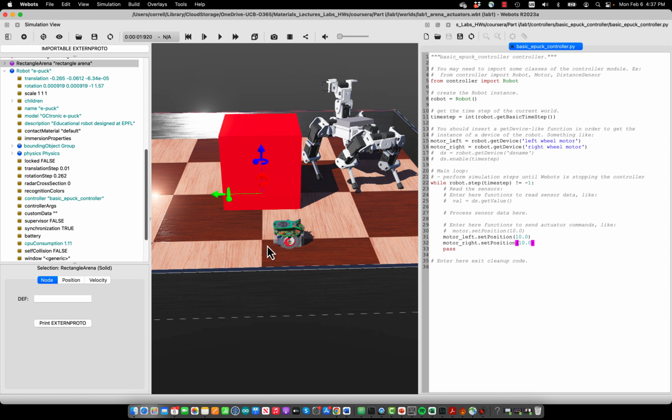But now, did you notice something? It's very inconvenient to drive the robot around by setting the position of the wheels. This makes a lot of sense when you have a robotic arm or robotic leg, like in this Bioloid example, where you would set absolute positions in order to move the leg or the arms in a certain pose, and then probably even implement a gait that makes the robot walk. Now, when you drive a car, you are very unlikely to drive it by setting the position of each wheel continuously. Instead, what you would want to do is set the speed.